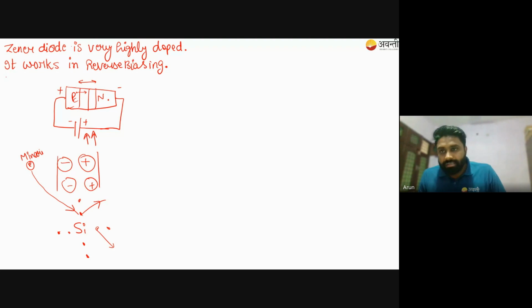So this effect of having a group of something from nothing, because initially we have one ice piece and finally we have an ice storm. Similarly, initially we have one minority electron, but finally we have a huge amount of electrons. So this effect is called the avalanche effect.